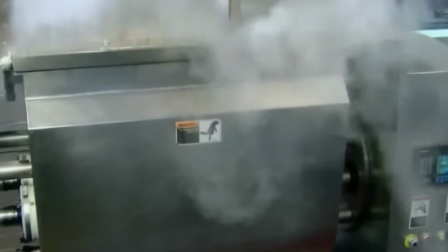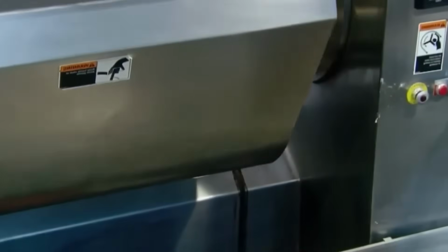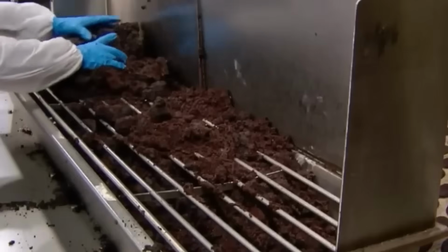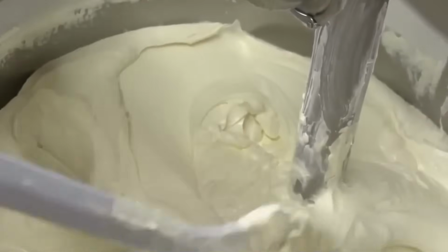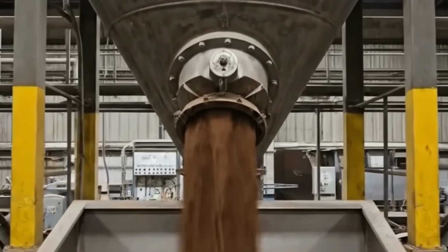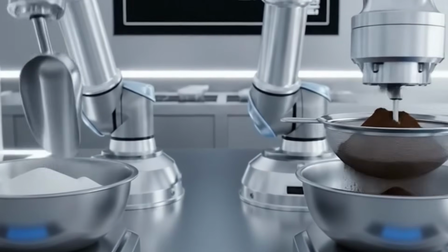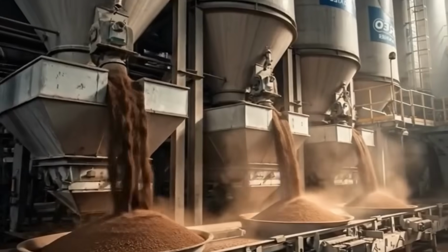Individual rolls are aligned using vibratory feeders and grouped into packaging sets based on SKU configuration. Film is dispensed from reels and formed into tubes by collaring mechanisms. Horizontal seal jaws apply pressure and heat at 135-145 degrees Celsius for 0.3 to 0.5 seconds to close the ends and seal the longitudinal seam. Nitrogen gas is flushed into the package before sealing to displace oxygen and slow fat oxidation.